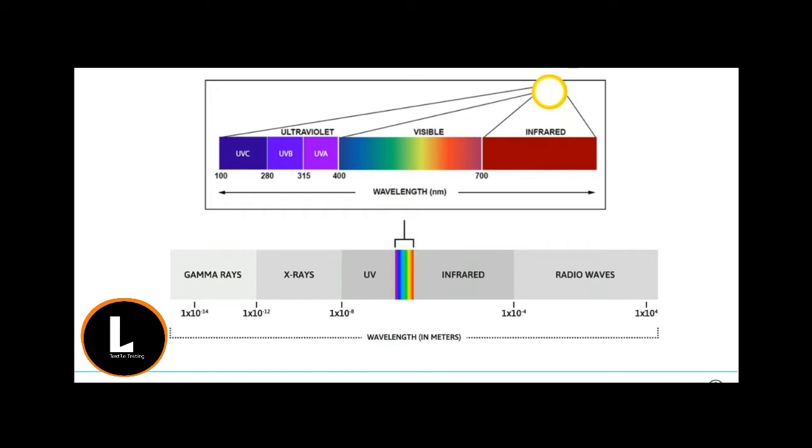And these have the most impact and ability to break down some of the dyestuffs, which causes the fading in some textiles. Although only a small percentage of the whole sunlight spectrum, about 7%, UVB and A are considered to be the largest contributing factors to the death knell of an unstable dye. The xenon arc lamp in a light fastness tester produces a light spectrum very close to that of daylight, of sunlight.